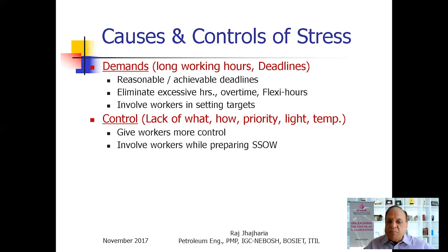Involve the workers while preparing safe system of work. Remember SSOW we discussed day before yesterday? So those procedures should be prepared in consultation with the workers. Often it has been observed that those who prepare these procedures probably have never worked on the shop floor, or they are far removed from the actual experience. And therefore it is very important to involve those who are working.